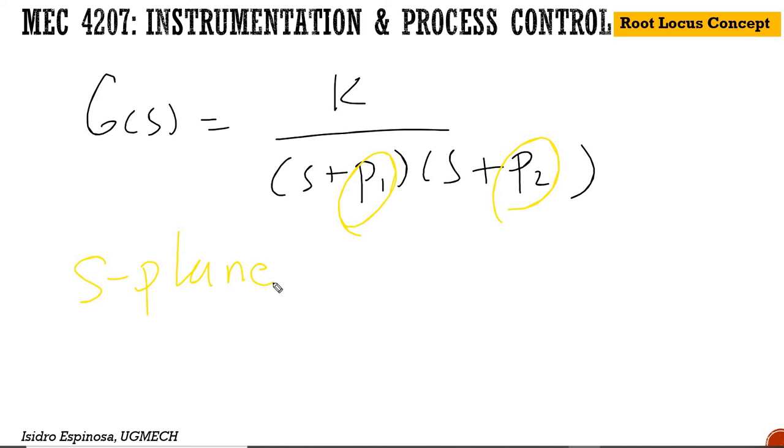So the root locus, as we mentioned, we need to understand how we determine or calculate the roots, and as we see in stability basic principles, how the transfer function can give you two important data values: the roots of the numerator that we call zeros, and the denominator that we call poles, right?